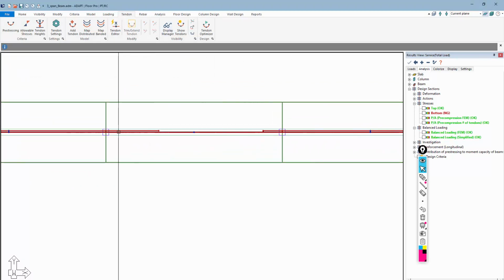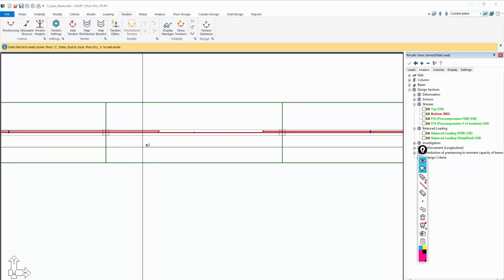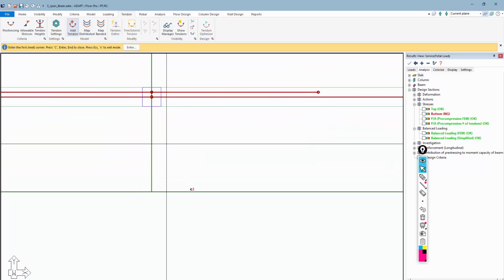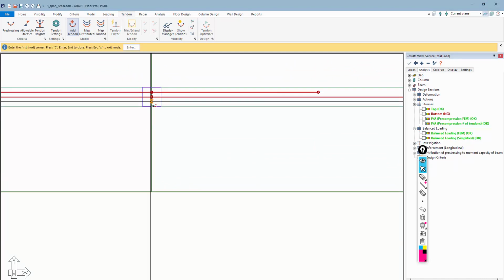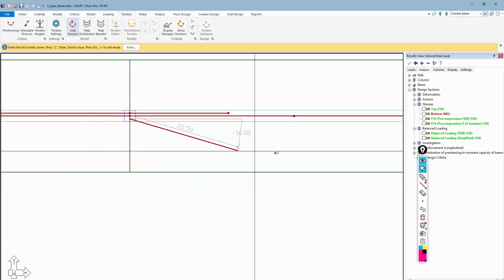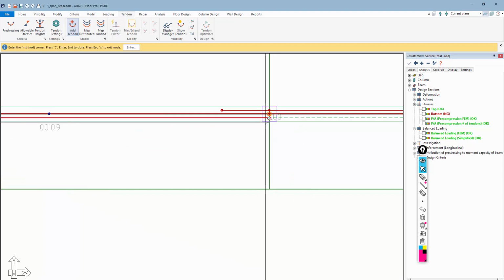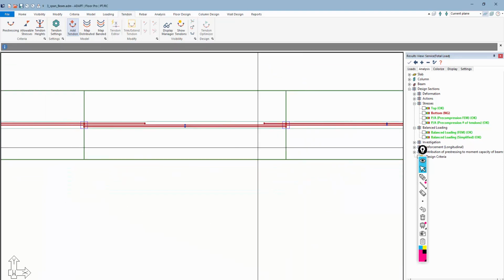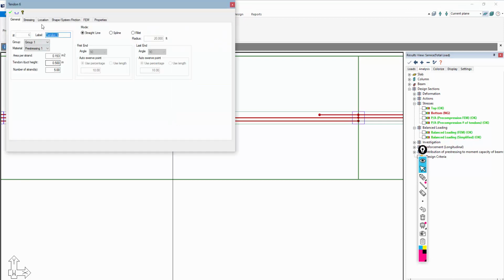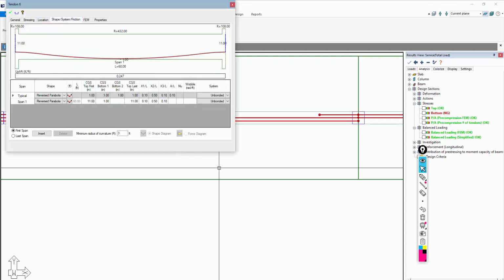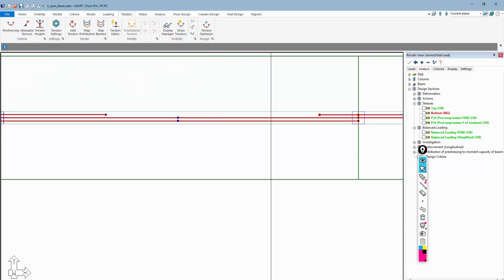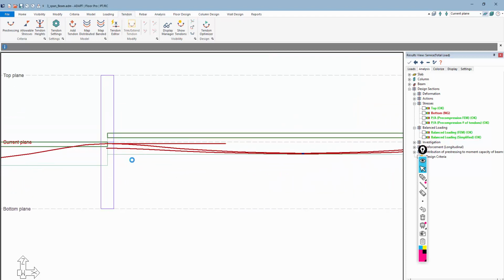and then we're going to do one right in the middle. So on the middle one, I separate these on the beam so I can actually see them in plan view. We're going to just start our tendon here, let's say, and we're going to stop that thing over here. So I'll turn back off snap near so I can snap perpendicular, and now I have this add tendon here.